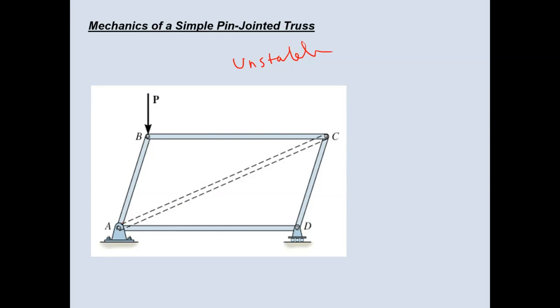That is why in most buildings, such as wooden buildings, between the frames they put something like a cable. They put cables in both directions. In case the loading is such that one cable becomes useless, the other cable becomes under tension, because a cable does not take compression. But if someone applies a different load, then the first cable could become ineffective and the second cable effective.